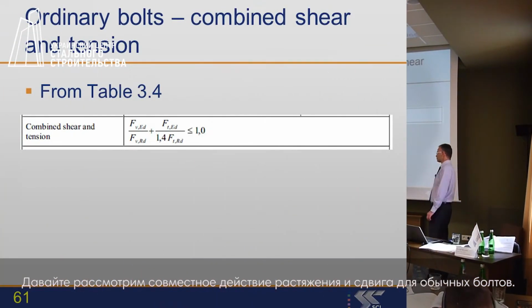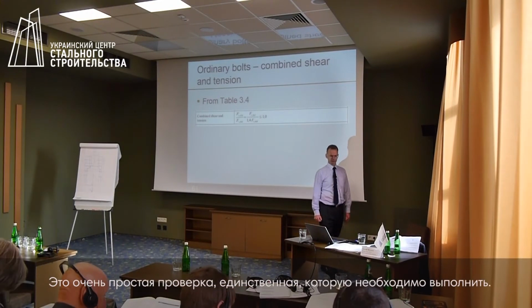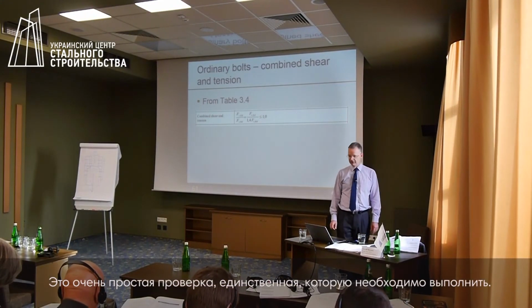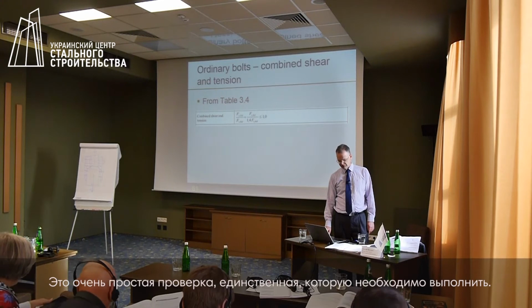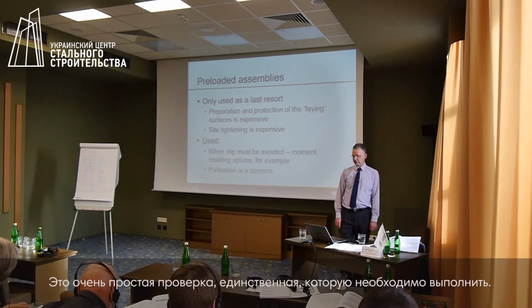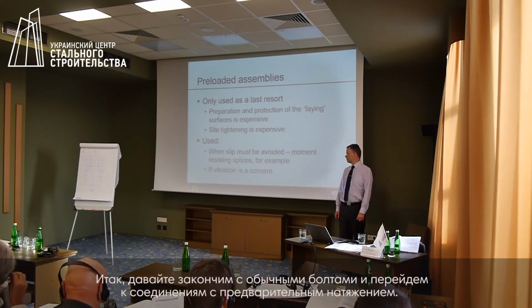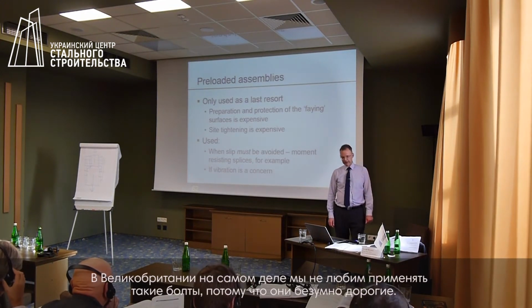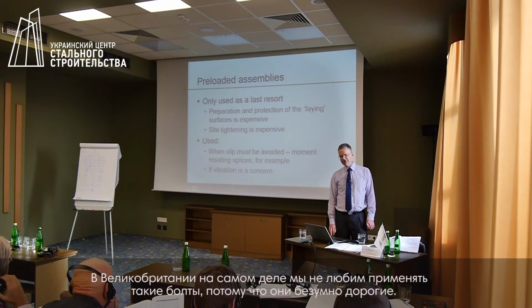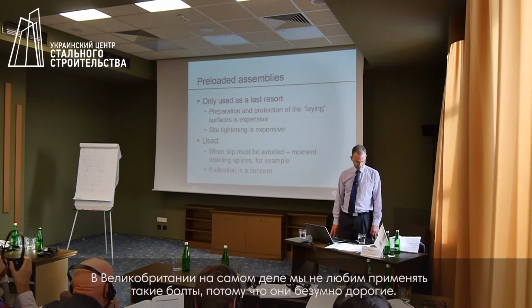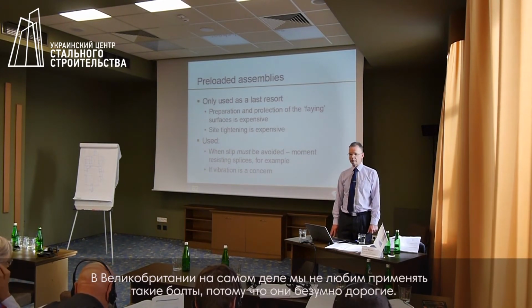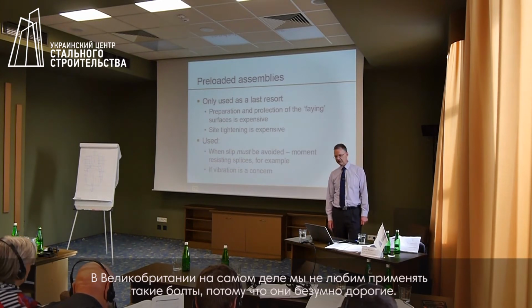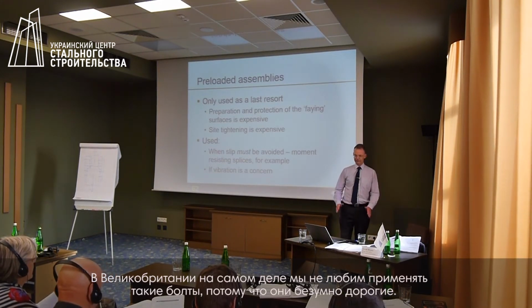So there is a relationship if bolts are in combined shear and tension. It's a very simple interaction, and that's the only check that we need to perform. So we will leave ordinary bolts and we'll move on to preloaded bolts. And in the UK, these are like death warmed up. So we would not like to use preloaded bolts because we think it makes the connections very, very expensive.